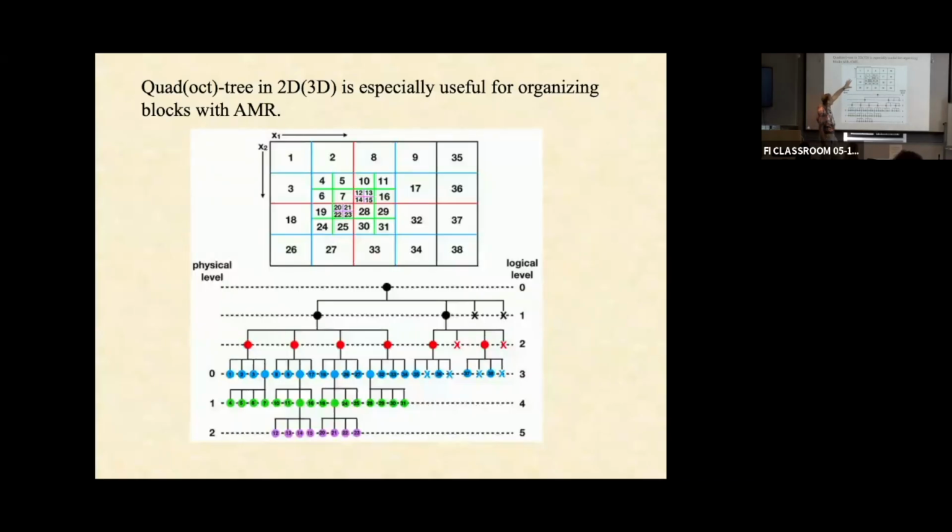If I go back to this example of a 5x4 mesh block, and then I imagine there's one little region where I want to refine it through 2 more levels, then if you have an oct tree, it's very simple to do that. You just insert new nodes. Whatever node you're going to refine just becomes another node of another level in the tree. And if you want to further refine that node, you insert another node again. And then you just automatically number the blocks again.